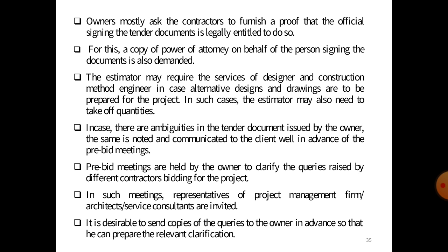Pre-bid meetings are held by the owner to clarify the queries raised by the different contractors bidding for the project. In such a meeting, representatives of the project management firm, architect, and service consultant are invited. It is desirable to send copies of the queries to the owner in advance so that he can prepare the relevant clarification.